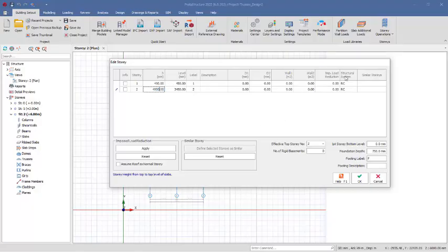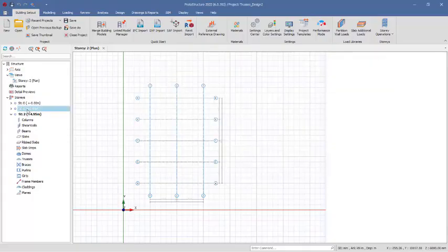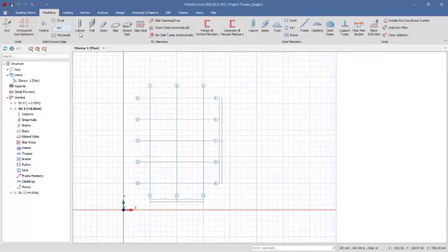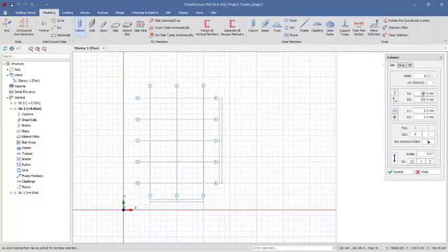Okay, so come to the structural system, very important. At the foundation, we have it to be concrete. At the substructure, the superstructure, we have this to be steel. So click on OK. Alright, navigate to story 1. Then go to the modeling tab, click on the column. So we are going to be inserting a column of length altogether 1200 from the DPC to the foundation level.